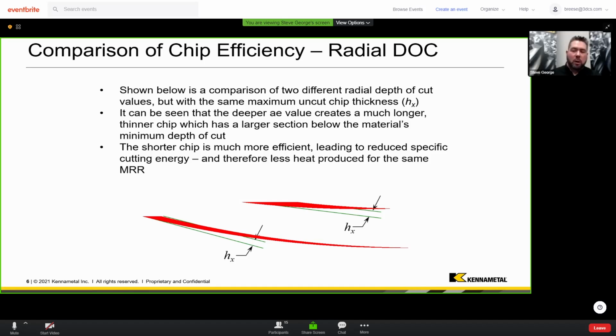We just talked about how we've got an elastic region of this chip formation, and a plastic region of this chip formation. Finally, we get enough deformation that we start to shear and make a chip. But we're significantly straining the material in this zone, and we're creating a lot of friction and a lot of rubbing. We're causing dislocations, but with no real output.